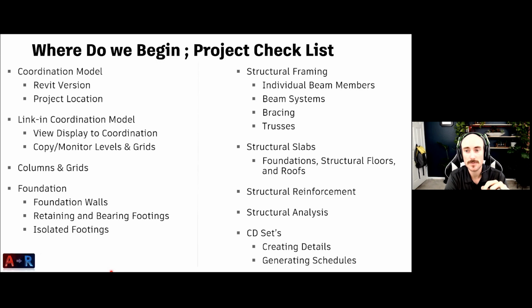You can also go through and place bracing, trusses. A quick tip for trusses: if you have an oddly sloped or ridged roof placement and you're trying to create a custom truss, instead of going through the long task of creating a custom truss, if you already have a layout that is similar for the webs and top and bottom chord, use that and then use the attach to top feature. So get ready to place your truss command. Then when you've placed it, you can select the truss. You'll have an option in your command line at the top, or in your ribbon under a panel, and it will say attach to roof. So you will attach it there, then it will follow the design of that roof.